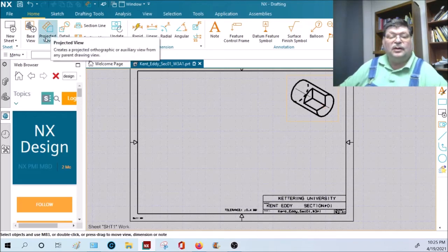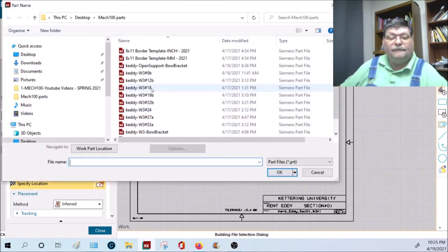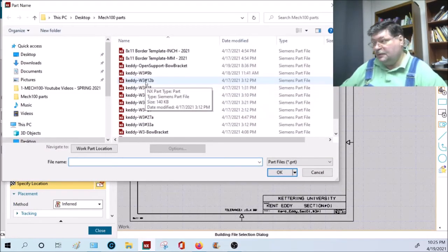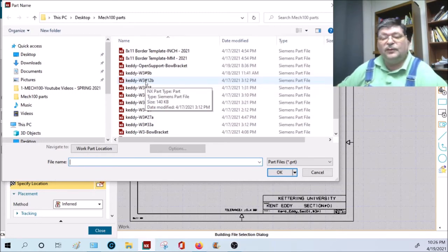And we do this with all of them. So we go to the next one. You should also put your template in the same folder that all your models are in, okay? Because when you go to open the template again, it looks in the same folder as the template was for all your parts. If it can't find them, even though you might have brought them in from a different folder, it's going to look in the same folder the template is. If it can't find them, it can't update them if you've worked on them afterwards. So put all your models in the week 3 folder, put the template in the week 3 folder too.